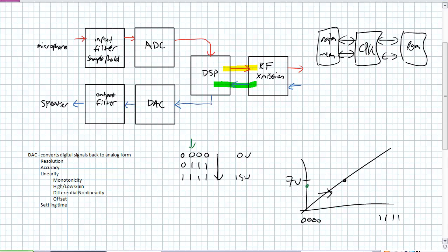Finally, settling time. It takes time for this thing to come through, and be aware if you're handling speech at high rates of speed, perhaps over long distances, there might be a delay that's involved. Most of the time it's not noticeable, but be aware that you want these things to occur, and if it's happening at an incredibly fast rate, these things do not occur instantaneously. Be aware that there might be some time for it to go through the decompression, the unencryption, the error correction, then the actual conversion of that digital information back into analog, going into your filtration, your reconstruction filter, and your amplifier. It's going to take time. Okay, so be aware of these things in your specifications.